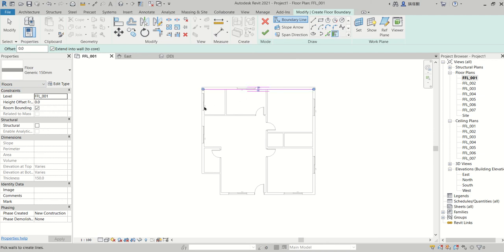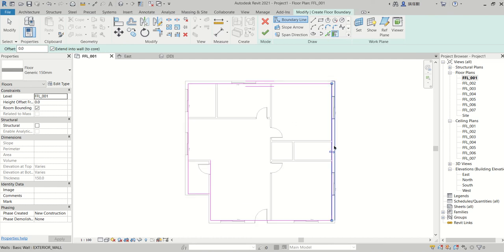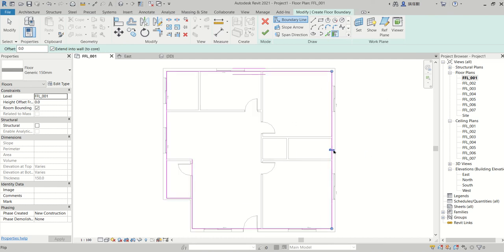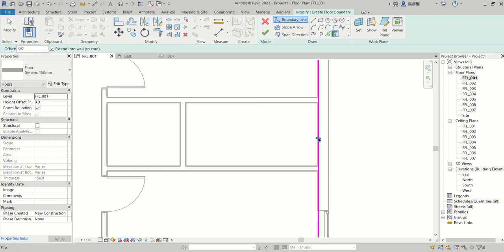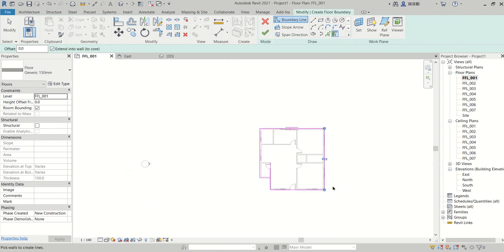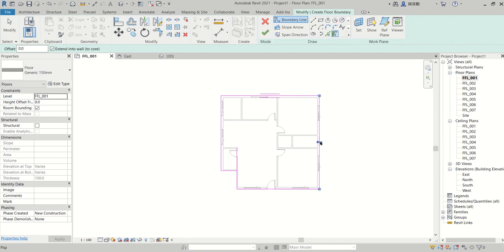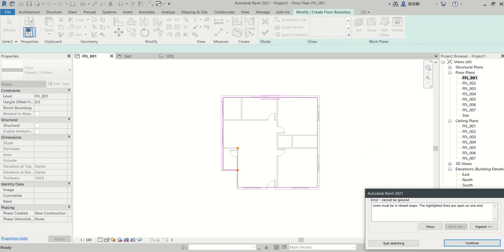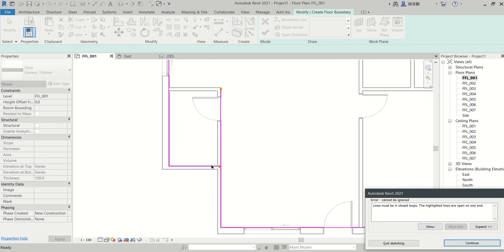You can choose all the floors which you want to give. So this is pick wall. As you have seen with pick line, this detects the walls. And also the last line what you have chosen, if you see these arrow marks, you just click them so that it will be flipped to the outside and exterior floor. This is interior floor. So I want to keep it as interior. I say okay. Yeah, you can see this pink line should not have any intersections.